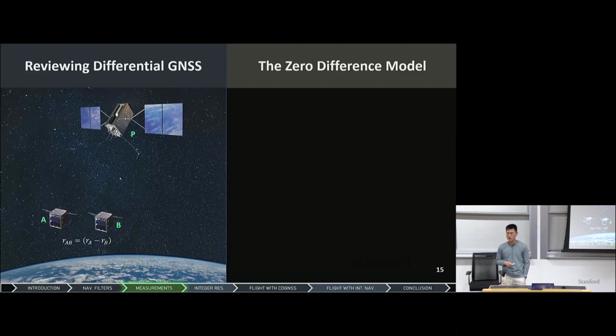I'm going to focus a bit more on the carrier phase model today. When your smartphones receive signals from GPS satellites, there are typically three observations of interest. Pseudorange is encoded in the signal, so the range you're receiving is unambiguous. You can think of it very simply as starting a stopwatch on a GPS satellite and another on your receiver, calculating the time elapsed, and based on the speed of light getting your distance, while also accounting for receiver clock biases and things like that.